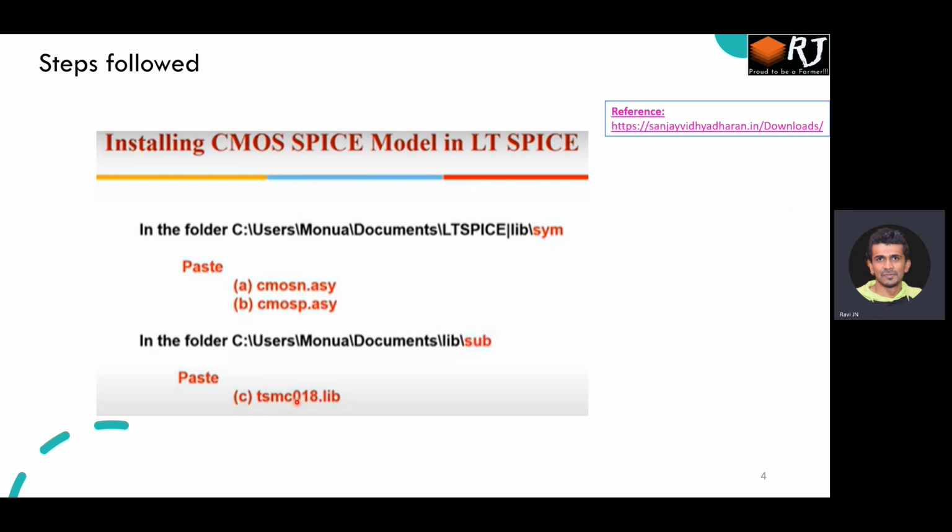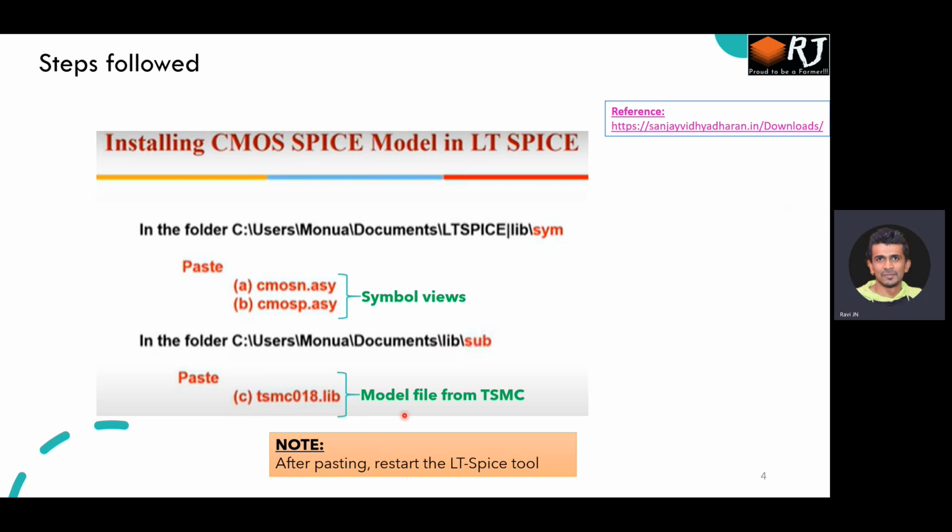As I said, I have taken the dot libs from TSMC 180 nanometer. So 180 nanometer is the target for me currently. I am using the library file from that, and the characteristics are based on 180 nanometer, that is, the minimum gate length of the devices. These are the symbol views. The last one is the model file from TSMC. After loading all these files and keeping them in the specific locations as specified here, make sure you relaunch LTspice, because it will read the database available in your installed location.